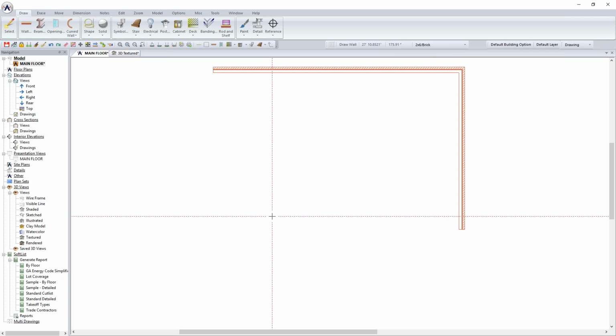Now, to understand a little bit about drawing walls within the program and different angles, by default we will lock you into a horizontal and vertical ortho at this stage. And so simply when I click to start and move my cursor left to right, that fell within that, and then I automatically moved it down vertically because that's the direction I wanted to go.